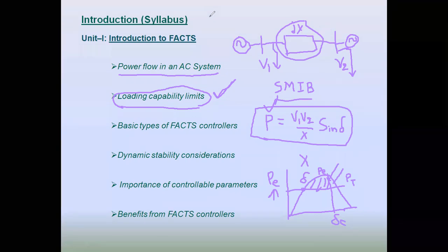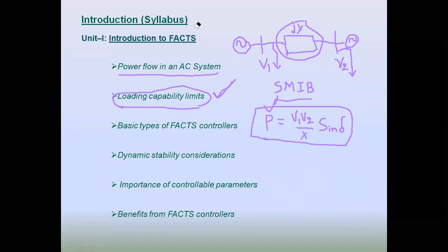This further study we analyze later, that is the shunt compensator or series compensator, while discussing the objectives. The loading capacity mainly depends on the stability considerations, dielectric strength, and also the temperature, that is the thermal capacity of the transmission line. And again, different stability parameters: voltage stability, that is the reactive power control, and frequency collapse, which is the frequency stability.